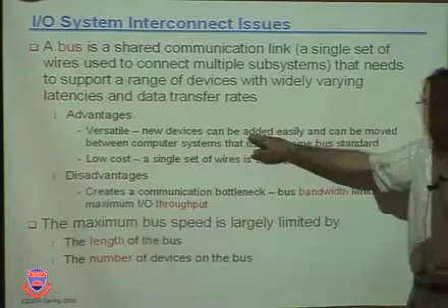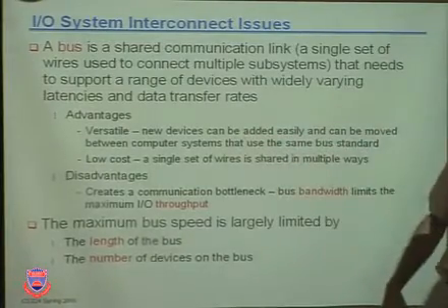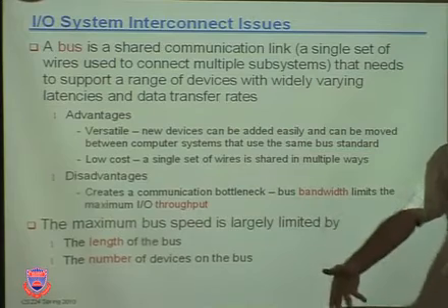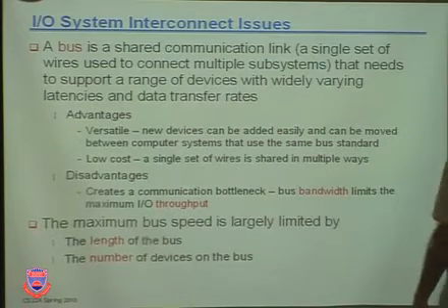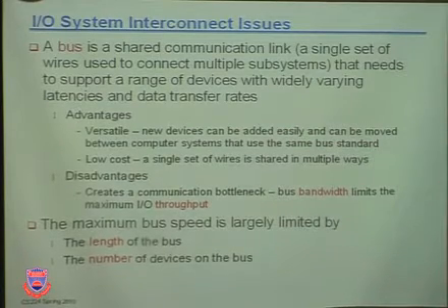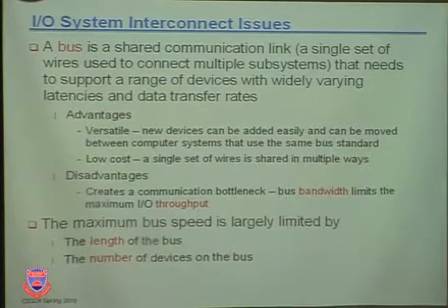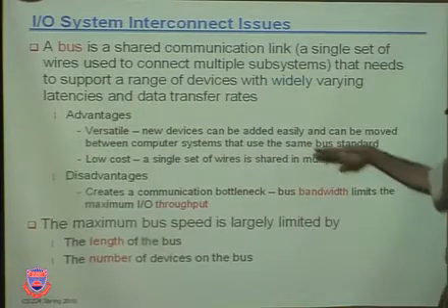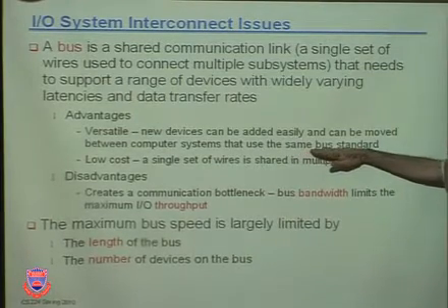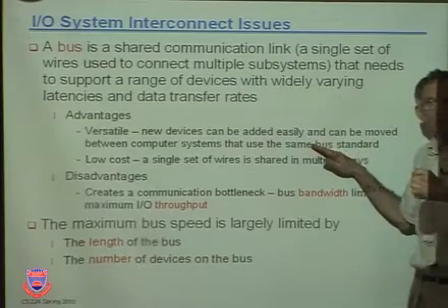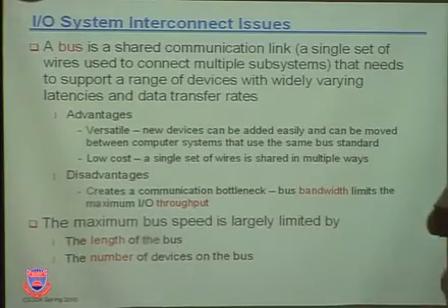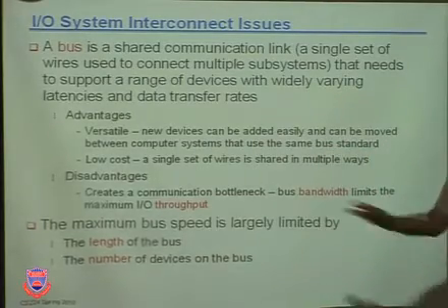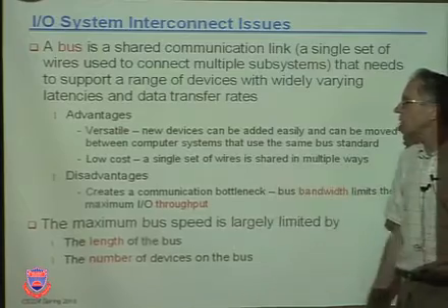And it's versatile. It means that we could add new devices easily. Once we have a bus, then we can put you on the bus as well. We have a bus, 4 users. You can become number 5, as long as you know how to obey the bus's protocol, voltage levels, timing signals, etc. So if you have the right bus interface, you can join the bus. So therefore, you have bus standards and devices that are made to adhere to that standard, or plug and play. You put them on and they're on the bus, and now you added a new I/O device.